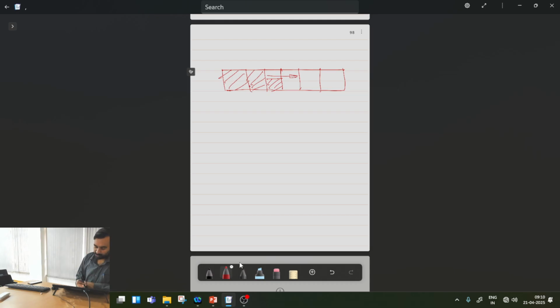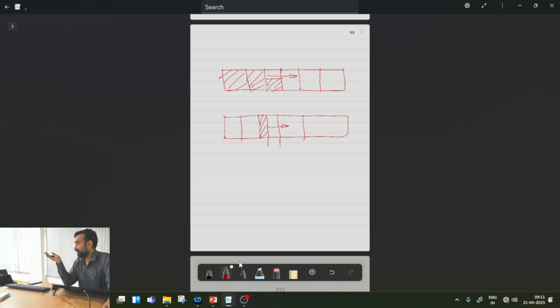Once the normal was pointing in that direction, whenever we took the distribution of the volume fraction, we placed this C amount of color function in such a way that the interface is normal to that direction. In this arrangement, we took the help of some geometrical parameters and then advected the interface. So for one-dimensional flow, we were able to advect the interface using this particular scheme with 100% accuracy.